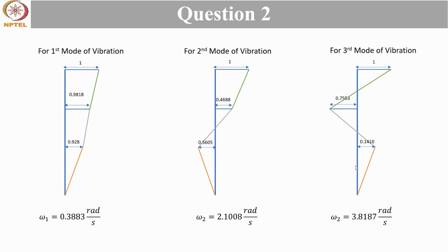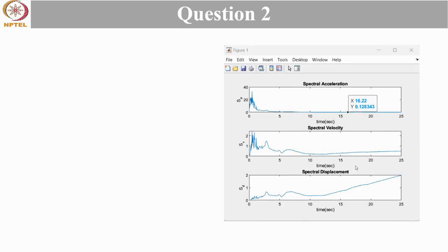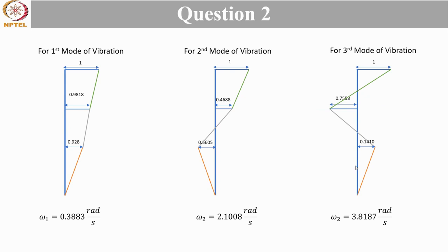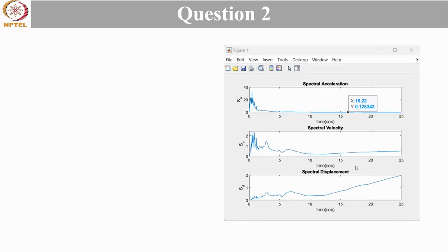So basically we can calculate the participation factor for each mode, and after calculation you will see that the first mode of vibration participation factor will be maximum. So we are skipping that part, and we will directly move on to estimate whether the non-structural element is safe or not for peak ground acceleration.